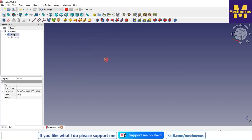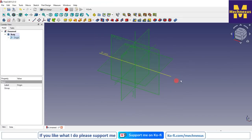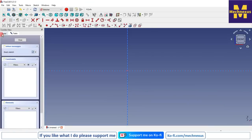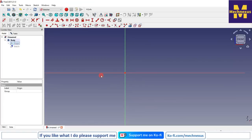you can see that nothing is visible in our user interface. So click on origin and press the space bar so that the datum planes and datum axes will be visible. Now here you will have the options to select the plane. I would prefer the front plane. I will select it and click on the sketch. Now go to the model tab and press the space bar to hide the datum planes and axes.